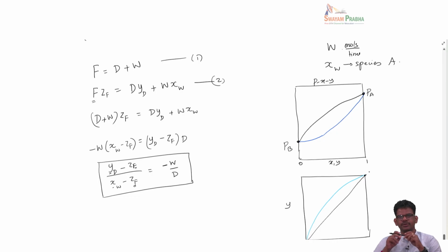So, what I am trying to do here is cast this process, the flash distillation, into an equilibrium diagram to make sense of what this equation means to us. Again, let me recall to you that this is a PXY diagram. The top one is the bubble curve and the bottom one is the dew point curve. At any given pressure, these are the two equilibrium compositions.